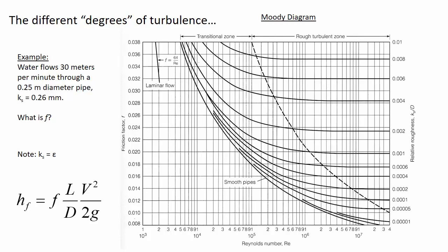We want the units to have a time component in seconds, because the typical water viscosity in kinematic terms is 1 times 10 to the minus 6 meters squared per second. All right. So will you put that into your calculator and tell me what is the Reynolds number for the water that's going through this conduit?